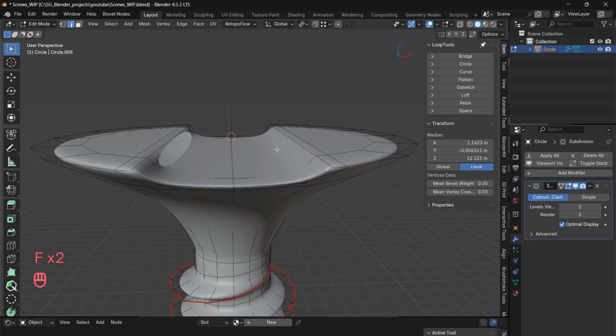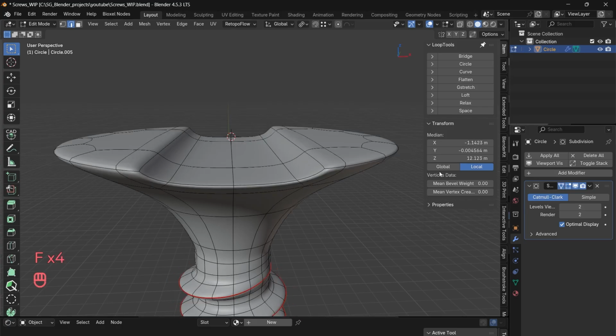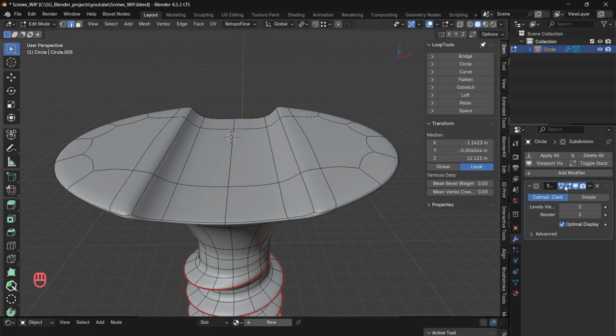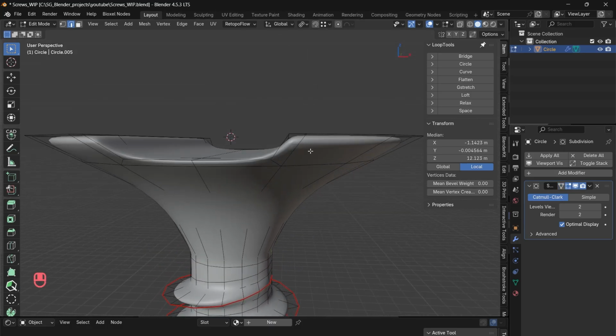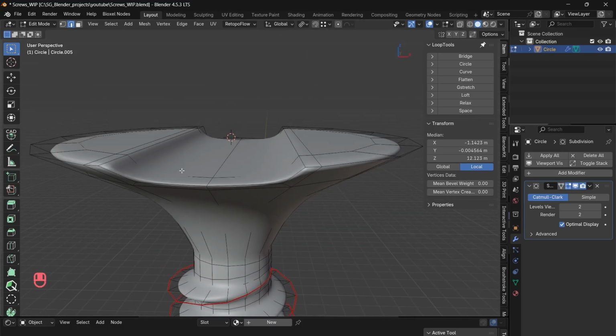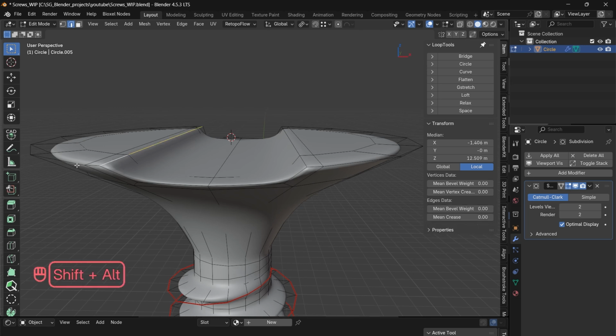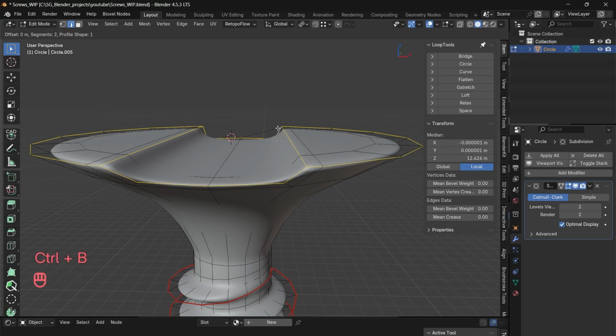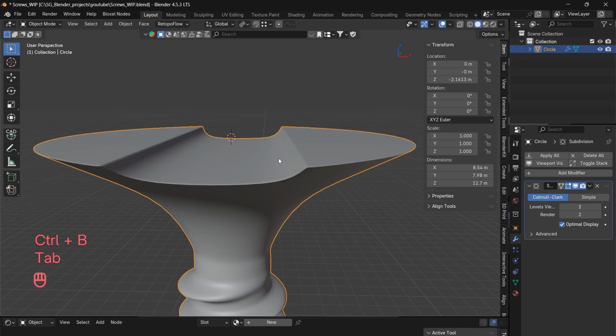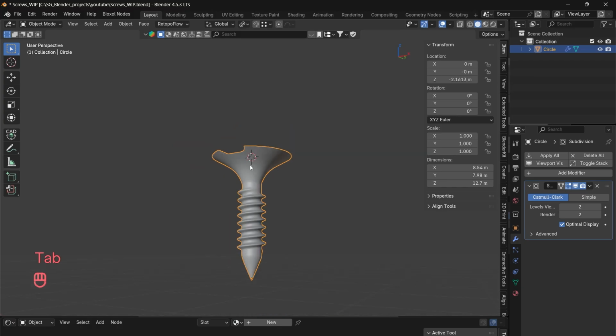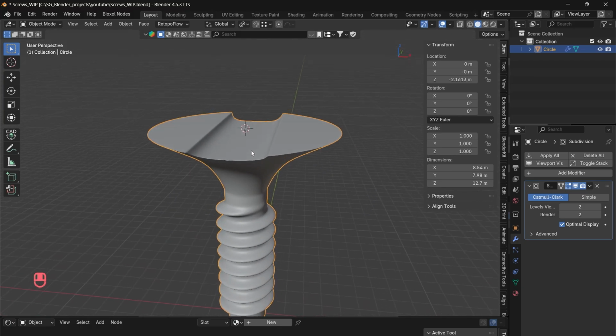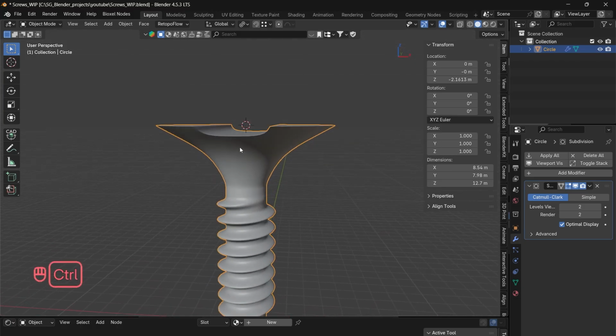Okay. Same applies for here. Same applies for here. Select the edge. Now, if I enable this in edit mode, it looks not that deep, right? Because I did not pay too much attention to the curvature of it, and that will happen if you follow with 16 vertex. So I'll just quickly add some bevel here, and I will call it a day for now. But with 16 vertex, it will be much easier to make it a bit deeper.